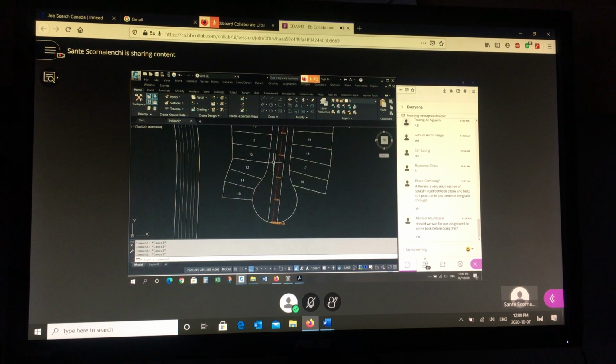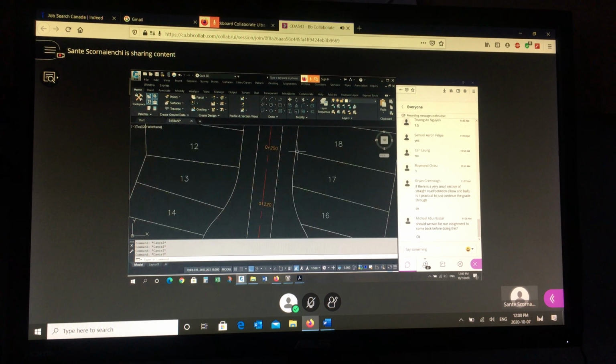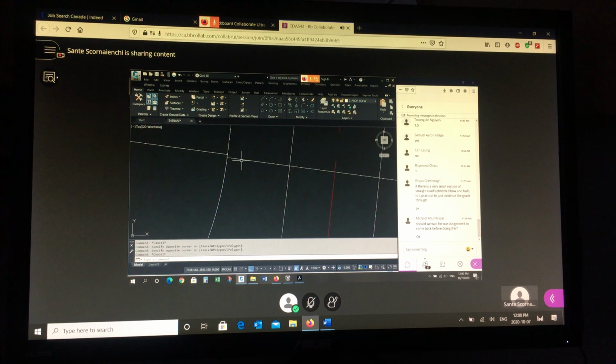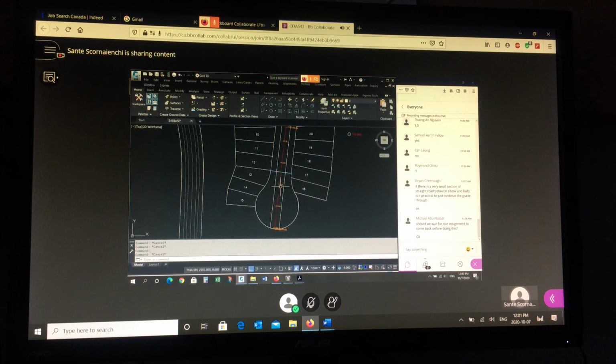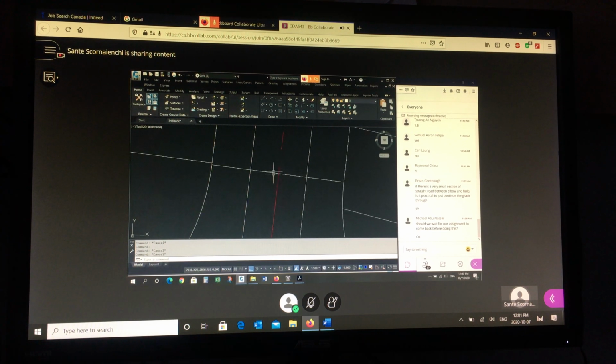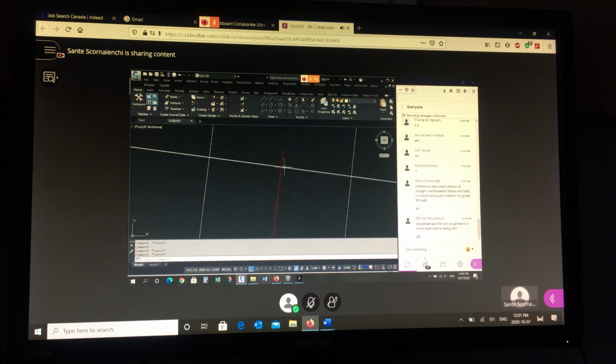So where's the last place I have a cul-de-sac? Well, I think it's right here on the right of way. From here to here, there's my standard 20, and then it gets wider. So there's where my cul-de-sac starts. Everything above this line is standard 20 meters wide. Everything down in this area is the cul-de-sac. So there's the entrance to the cul-de-sac right there. That's the first point on the cul-de-sac.